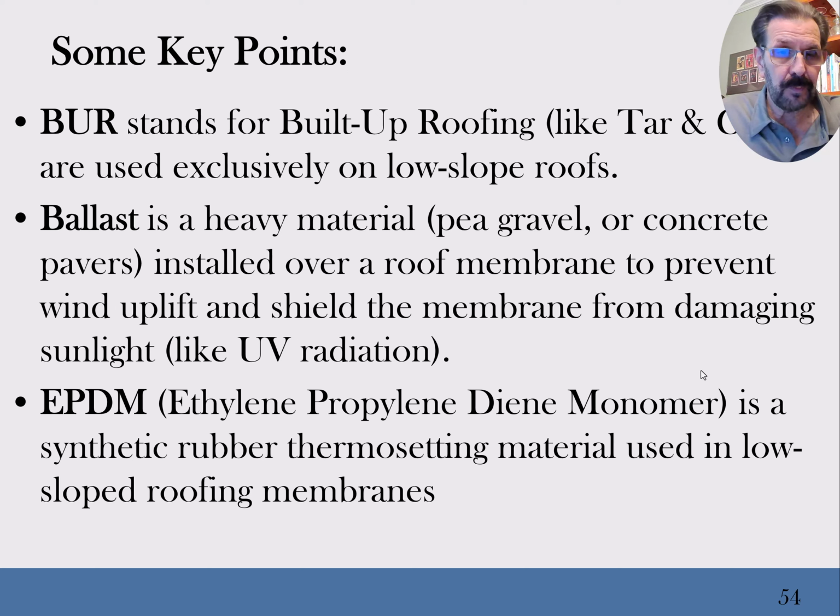A built-up roof, BUR stands for built-up roof. That's the tar and gravel or asphalt and gravel roof that is used exclusively on low-slope roofs. Ballast, that would be the gravel, the pea gravel that we put up on the roof. We call it ballast. In a submarine, we talk about the ballast. We adjust the weight by how we compress the air in air tanks, and they call that a ballast tank. The reality is, as they compress more air in there, we're adding more weight, and that can weigh things down. And then they can blow the tank when they need to go up. But here, it's the other way around. The gravel is the weight, it's the ballast, or the concrete paver.